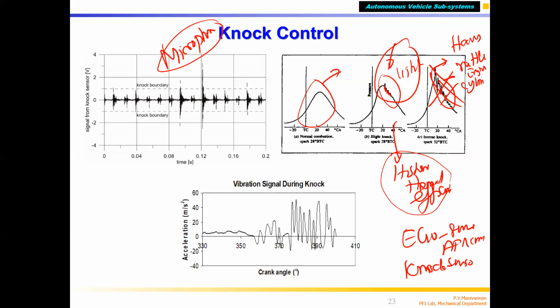So what you have to do is reduce the gear and then start accelerating. But if you're a new driver, you cannot coordinate all this. This will happen, don't worry, but try to avoid it. This is the knocking condition. So the knocking condition can be detected by measuring sound or vibration using a microphone, or you can use an in-cylinder pressure sensor.